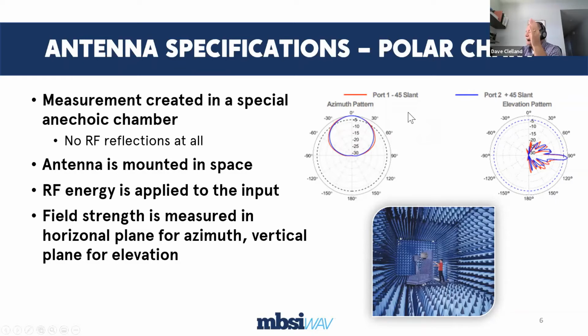The antenna manufacturer will do the same thing and go around the antenna in the vertical, or tip the antenna to the side and use the same test measurement and go around measuring the vertical pattern of the antenna. We can see that in this particular case, the vertical pattern is much tighter than what the horizontal pattern would be of the same antenna.